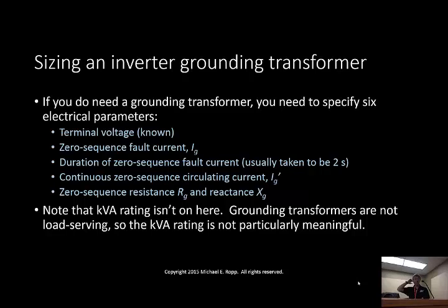That's where that came from. Now I will tell you, we've actually been using a longer time for this. About 10 seconds is our recommendation right now. I'll show you the reason why in just a minute. It has to do with coordinating the overcurrent protection of the GSU, of the grounding transformer. Okay, so I need that duration, and this is something that we just choose.